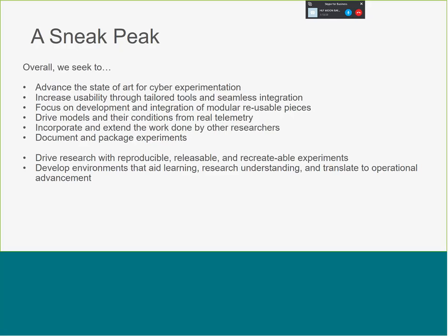Am I done with verification and validation? Have I done sufficient rigor? Maybe, maybe not. So what if you could then push a button that said, okay, I've confirmed that this works. Mutate and permutate that architecture in 10,000 different ways using real-world methods that determine different protection settings based on different topologies, different breaker settings based on different topologies, all that solve the same thing. All topologies that are realizable and mapped after the real-world thing, and you just have to press a button, and now you have 10,000 cases that say your stuff works, rather than just one. So that's where we're going.